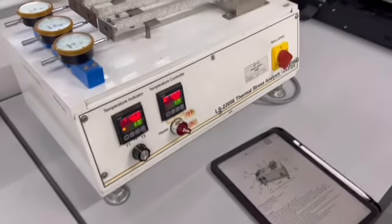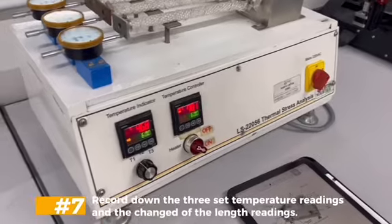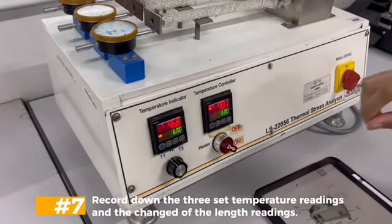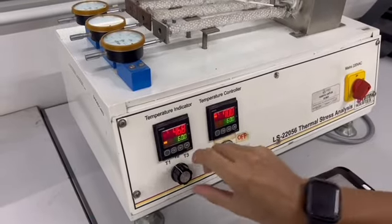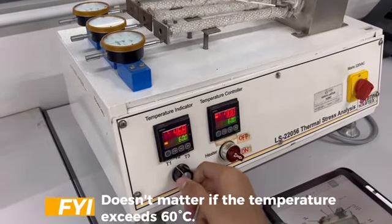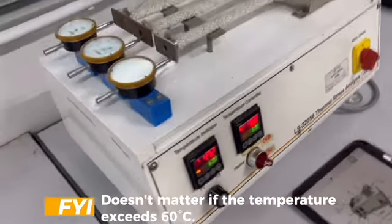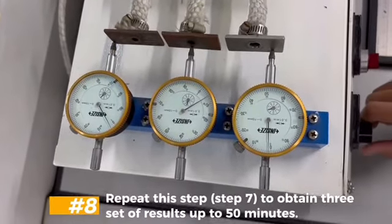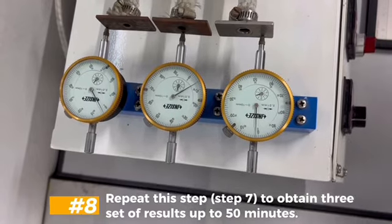After 10 minutes elapse, record down the 3 set temperature readings and the change of the length readings. For your information again, it doesn't matter if the temperature exceeds 60 degrees Celsius. Then, we need to repeat this step to obtain 3 sets of results up to 15 minutes.